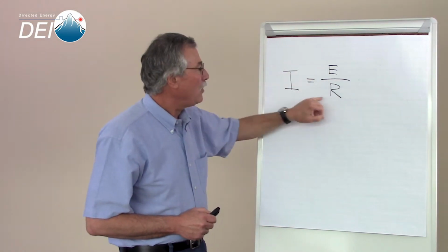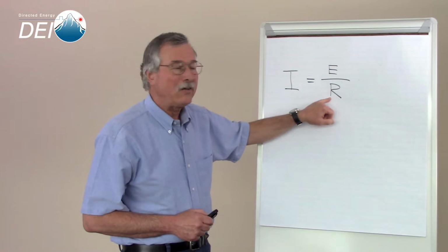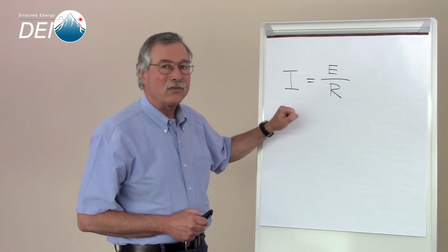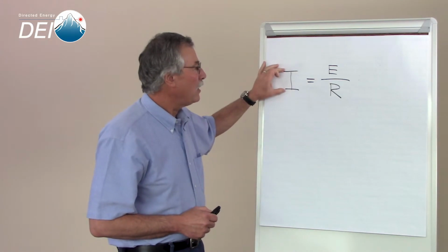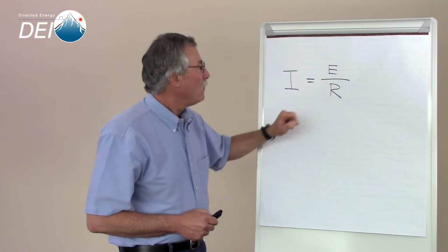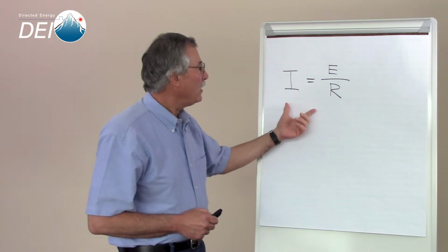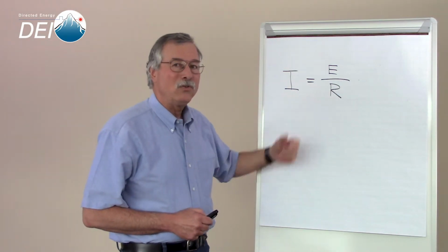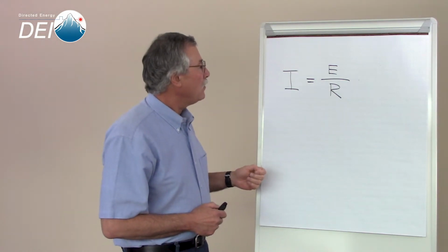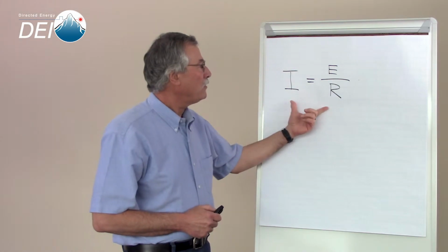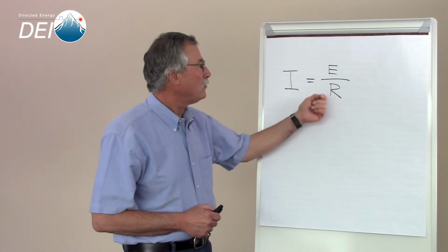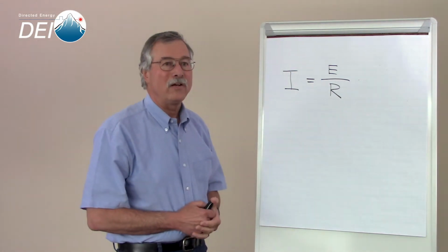The current will follow the resistance. If the resistance varies, the current will vary as well. On the other hand, if we have a current source and we hold the current steady, then the voltage will vary as the resistance. It should be obvious, but let me say it anyway. We can control only 2 out of the 3 elements. It turns out that Ohm's law will always dictate the third one, and therefore in a current source we let the voltage vary, and in a voltage source we let the current vary.